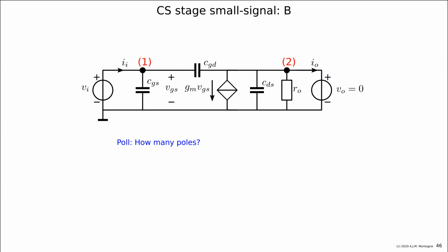We have 2 voltage sources. CGS is connected across a VI, which means if you put charge on CGS, it will instantaneously cause a huge current in VI, and the voltage will remain the same. So it's not a free voltage, because the voltage is set by VI and it cannot be free.